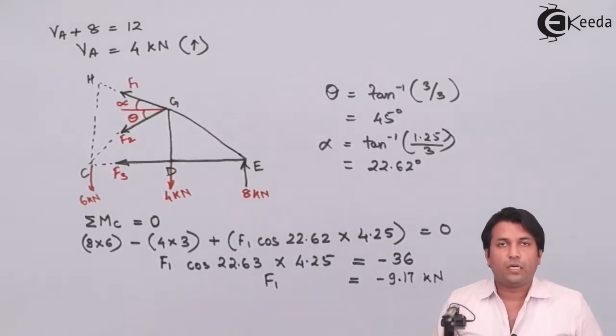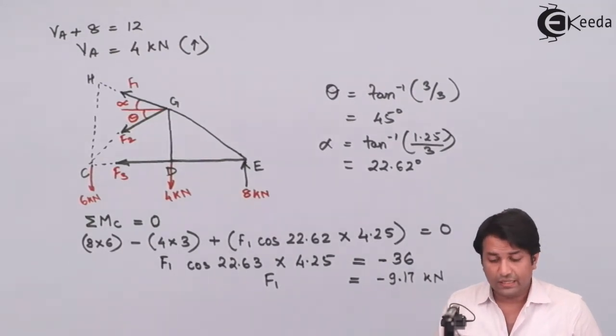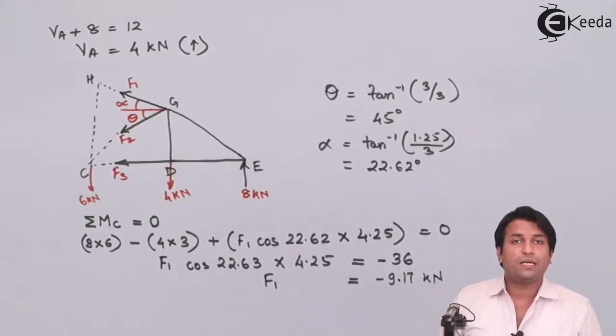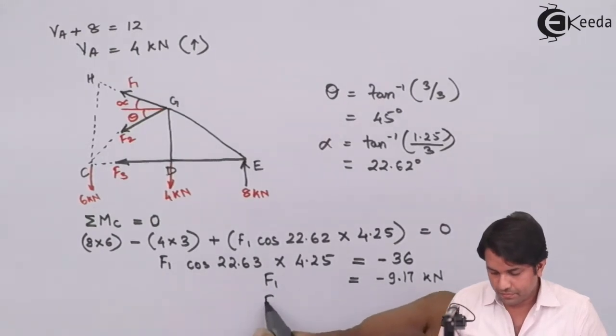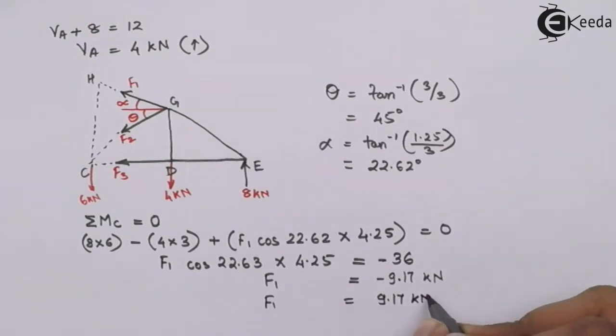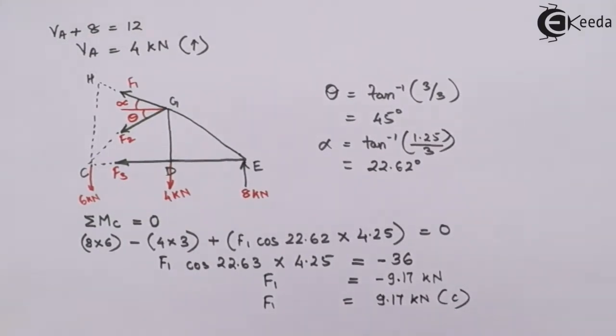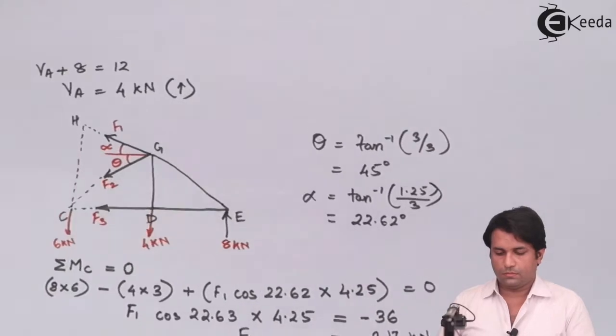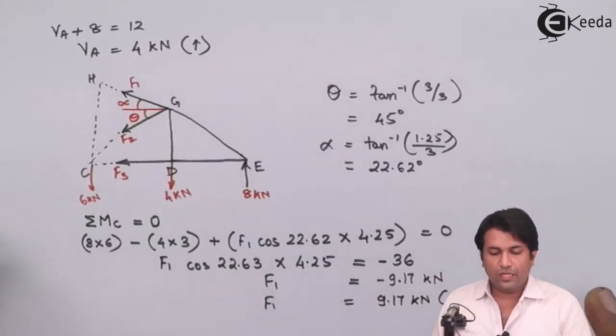That means what? The nature of the force in F1, that is the member GH, happens to be compressive. Now, I'll move on to the next point.